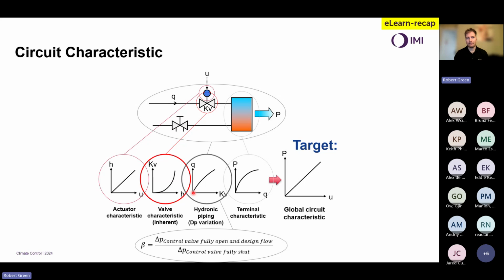And as we're going to learn tonight, this morning, should I say, for you, we're going to be looking at how, when we design systems in HySelect, it's going to select products for us effectively to ensure we have this good level of authority. And you may remember we talked about an authority range of 0.25 as a minimum up to a design maximum of 0.5. We could go beyond that, but in essence what we are then doing is applying more differential pressure in the system with limited output and limited gains in terms of improvement of control. So that's the purpose of balancing, the purposes of sizing of controls and looking at control authority.